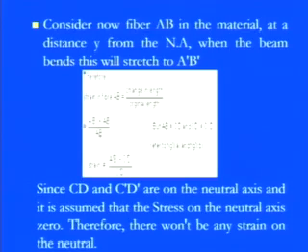So we can straightaway conclude that whatever the distance is before the bending moment is applied and after it is applied on the neutral axis, they have the same distance without any deformation or any strain. So we can say that CD is equal to C dash D dash, and if we apply those things here, the strain component is nothing but A dash B dash, which is the previous thing, and AB is equal to CD, and CD is equal to C dash D dash.